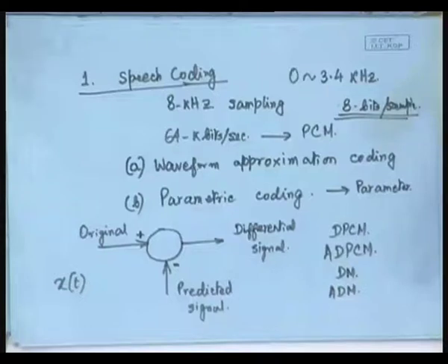Actually, for the speech signal or for the image signal, we luckily have a lot of redundancy present. Now, think about why for the speech we were talking about differential encoding: because successive samples of speech happen to be somewhat correlated to each other. If we pick up a sample at some instant, the very next sample is not going to be very drastically different from the present sample. So, instead of representing the absolute magnitude of that sample, we take the differential. Why? Because the differential is going to have a much lower dynamic range. So, we require fewer bits to represent that.